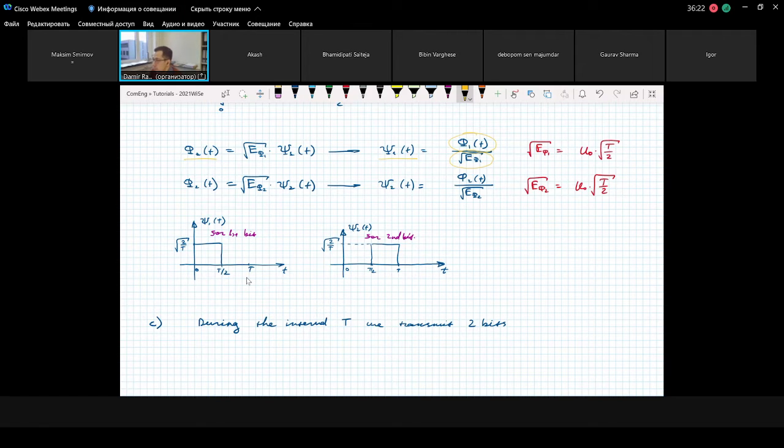We come to a simplified version where, in order to find the second basis function, we just need to, as in the first step, normalize the corresponding signal because they're orthogonal. And then if you have third signals that are orthogonal to the previous two, you just continue, just normalize.